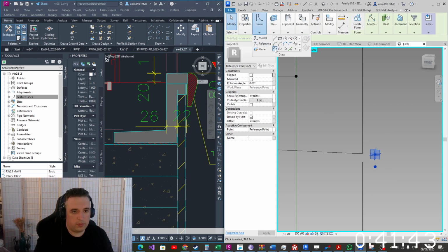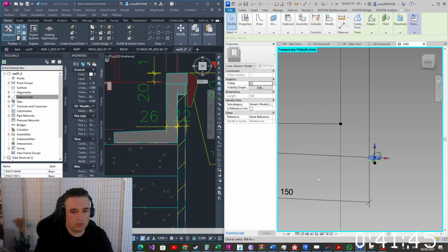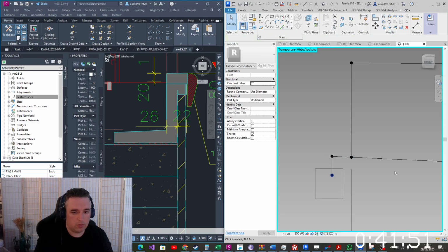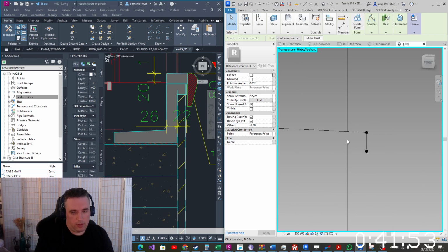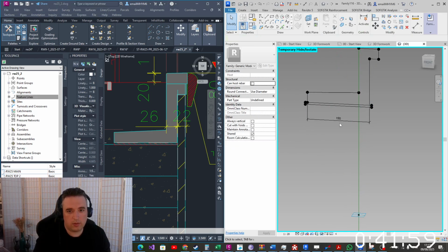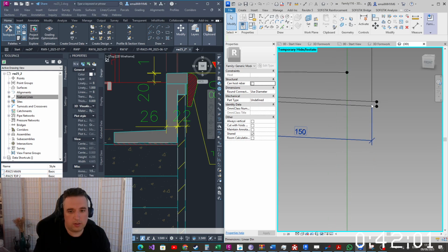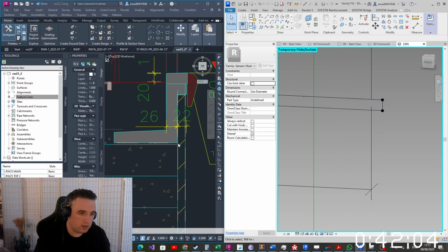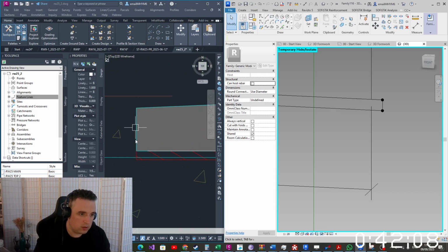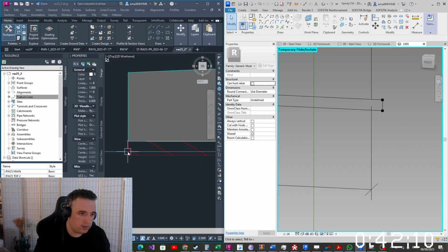Okay. Almost done. The advantage of doing it in the same family is, of course, you make the change once and everything updates. That actually sits against the wall here, so that shouldn't be 5 centimeters. Here they also didn't do 5 centimeters.